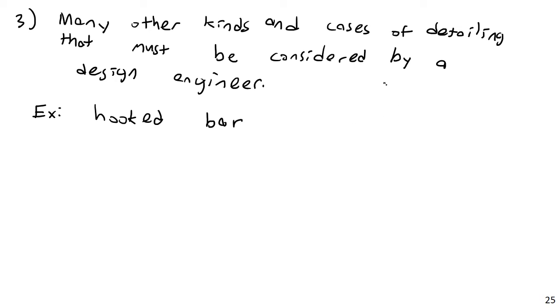So if you think about the normal steel that we've been talking about, we have a piece of steel embedded within concrete, and it's basically transferring that load via skin friction. Well, what if, if we find that we can't get enough length here, we made the bar into a hook? When that bar wants to pull out of the concrete, the only way it can do that is by tearing through a massive amount of concrete.